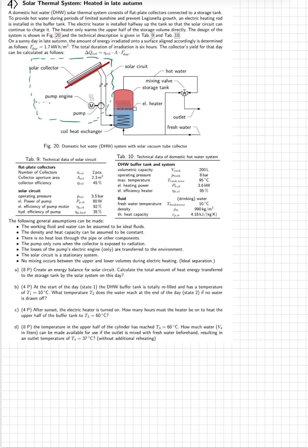Now here is the crucial part I want to ask you before constructing the energy balance. How can energy cross this system boundary? Here this is my system, so how can the energy cross the system boundary? There are three ways. One, the solar radiation enters here as heat. Second, electrical power enters through the pump as work. And third, thermal energy leaves into the tank.